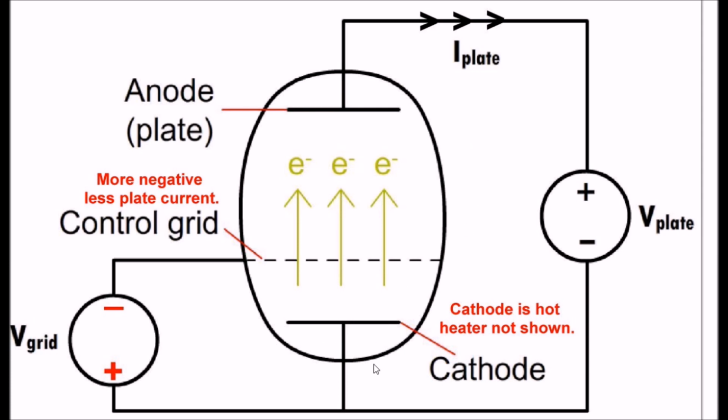You get a cathode that is hot. It adds enough energy to the electrons in the metal cathode. The cathode, by the way, is coated with rare earth oxide, sometimes thorium, I think, to be better. It's called thermal emission. If you don't have a positive charge on the plate and you just heat this up, the tube will fill essentially with floating electrons, which will, of course, the minute you apply a positive charge to the anode, you will get a current flow from plate to the positive terminal.